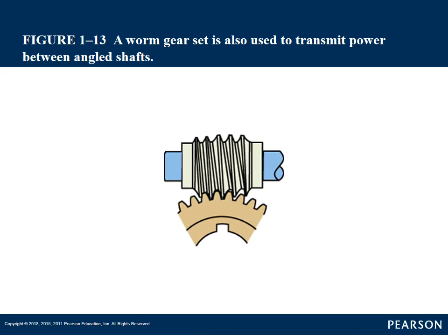And then a worm gear, this is where we got, again, gears on angled shafts or separate shafts. The lower gear would have a shaft that would be like if you were looking at it and the shaft was coming to us. That would be like the output shaft of a transmission, where there's gear going across. Then it meshes in there, and that'll be used, say, to drive a speed sensor or drive a shaft that drives a speedometer cable. That would be a type of worm gear that you might find in an automatic transmission.